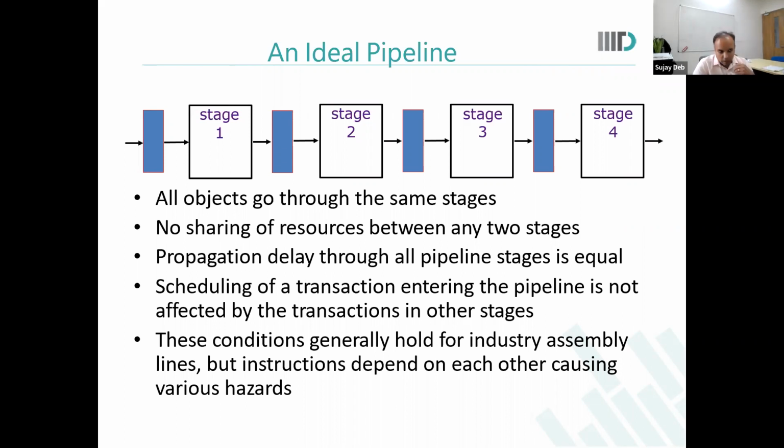So remember our goal: we have a bunch of instructions from our ISA, and now we are trying to build the hardware which will execute those instructions. First, we said that we will break this execution down into multiple stages. And now we also want to pipeline this execution.